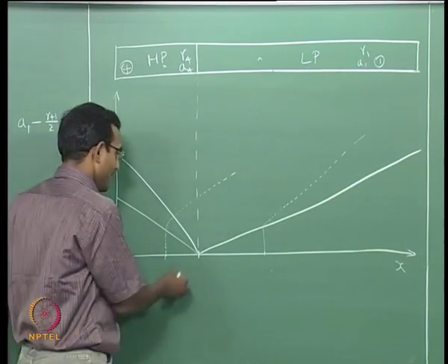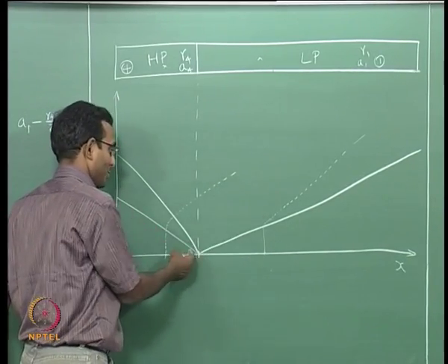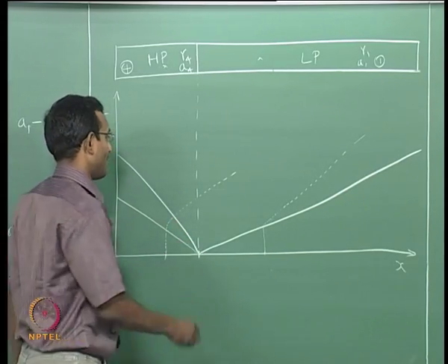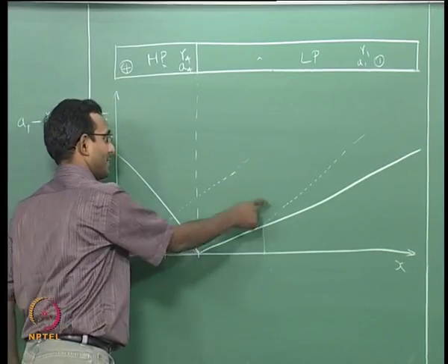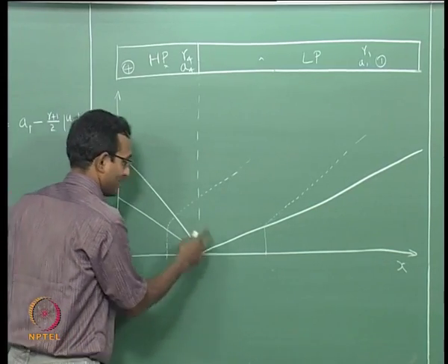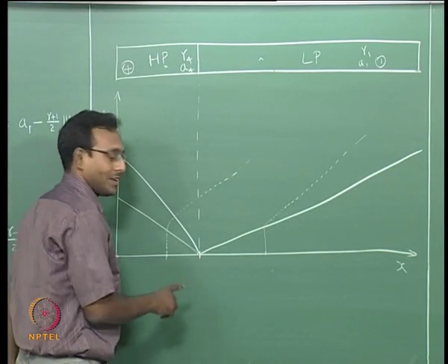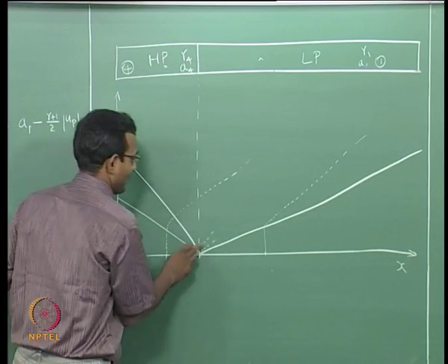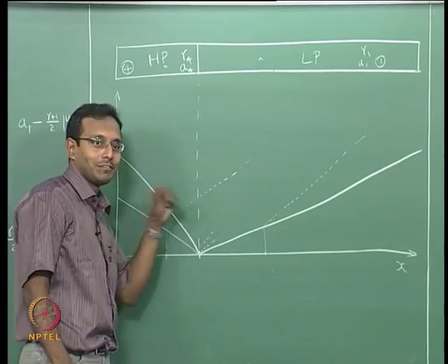Okay. In a very short time, probably within a microsecond or two, the strength of the shock, how much expansion fan should be there, all that is decided within that time. Okay. And finally, what should be the velocity of the fluid element behind the expansion and behind the shock, everything is set by them. Okay. Ideally it is not set when it is this far, it is set for the particular fluid elements very next to the diaphragm. Immediately after that, this wants to go this way, while this one wants to turn and go this way. If they are not going parallel, then they will interact and send out extra waves this way or that way to make it equal.